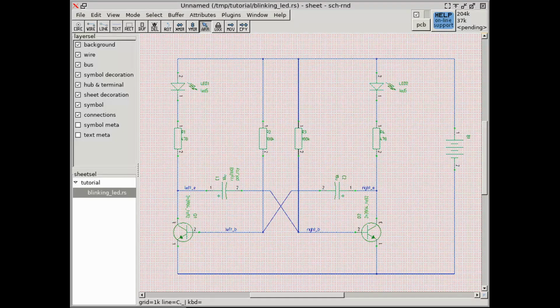The drawing we worked on so far is called the concrete model. There is an abstract model in the background, which is the real meaning of the drawing. For example, the concrete model has symbolic names N and P for some of the terminals, while the abstract model for the PCB workflow will contain the final footprint pin numbers. Compilation transforms the concrete model into the abstract model. The net list we need for the PCB layout is generated from the abstract model.